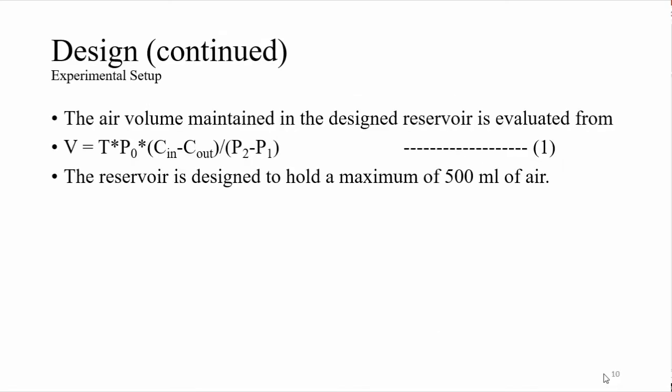So what is the amount, the volume of the reservoir required? This is the formula to calculate it. This is the volume of the tank. This is the pressure. This is the time for which your valve will be open. So this is approximately around 0.3 seconds.